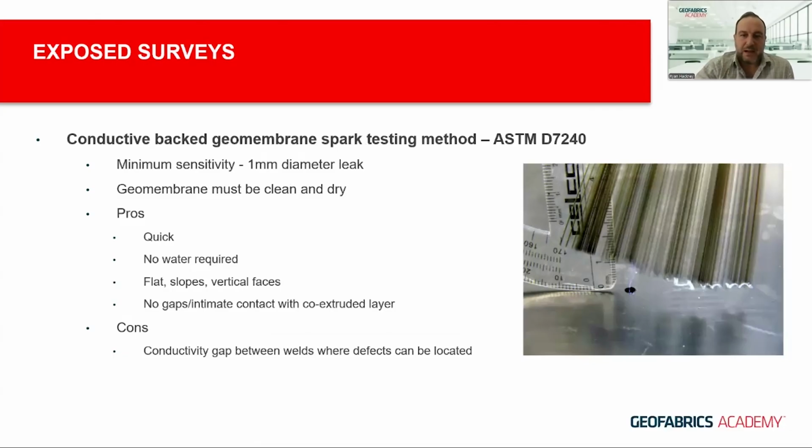Okay, so that was wet methodologies. There are also dry methods for conducting leak location surveys. So ASTM D7240 is a specific method for conductive backed geomembranes. So this is typically HDPE and LLDPE.